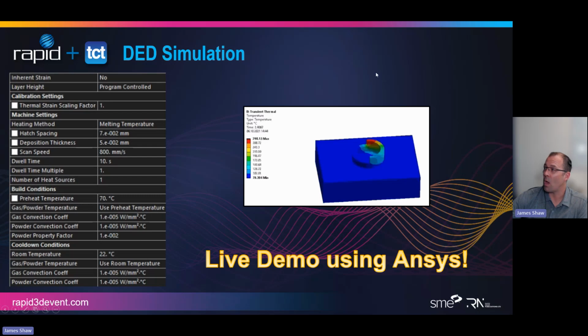And now I'm going to swap over to Ansys and show you how one gets set up. I've got a pre-built one here. And for the record, I am going to show you a directed energy deposition process. So we are going to see some of the layers get added. This is another example of a DED process. And as you can see, because of how slowly the material is added with respect to the total print time, in this case, you'll see what we call these sort of chunks or clusters of material being added. And so all of that can be controlled.